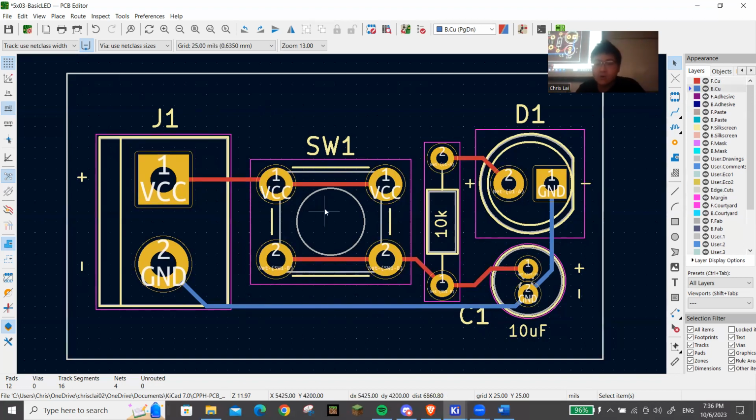So in this case, your default route width really matters, because if you have a thicker route width, you can pass more current through. There's actually a whole table that shows you what you can and cannot do. For example, 10 mils allows you to pass around 1 amp through the circuit without things catching on fire. For this circuit, I know I'm not going to pass more than 1 amp of current, so I don't have to use thicker traces. But if you're making a PCB for driving motors, for example, you're going to need larger traces because motors will pull a lot of current through the PCB.